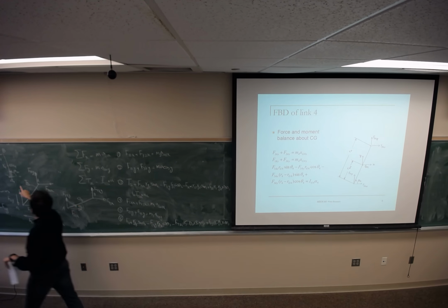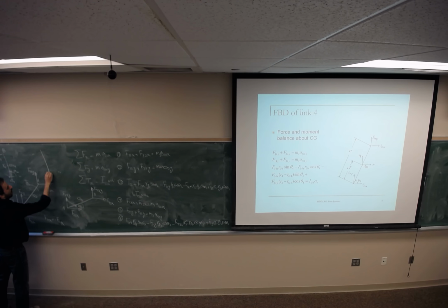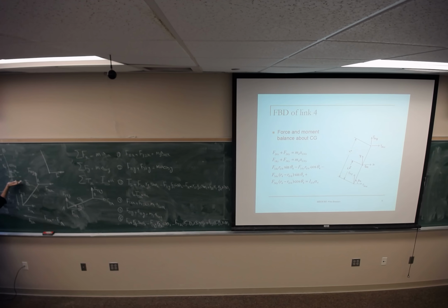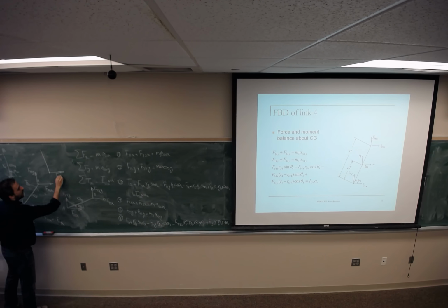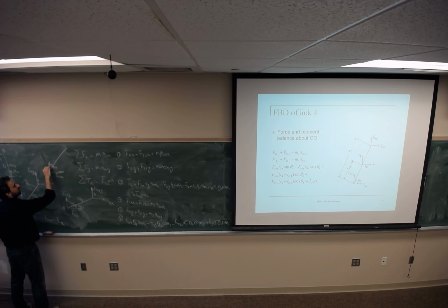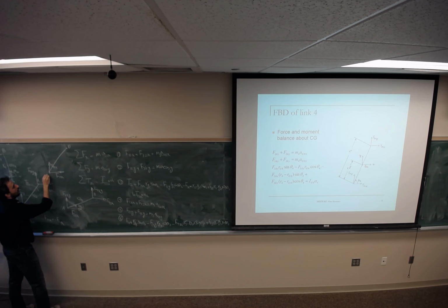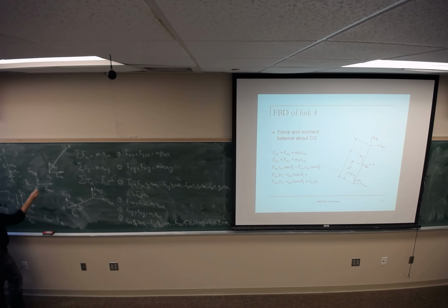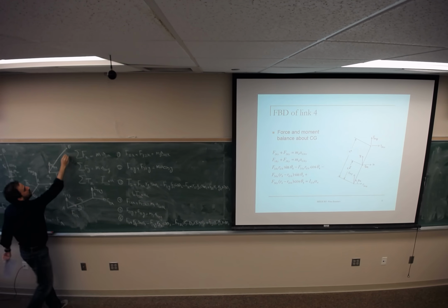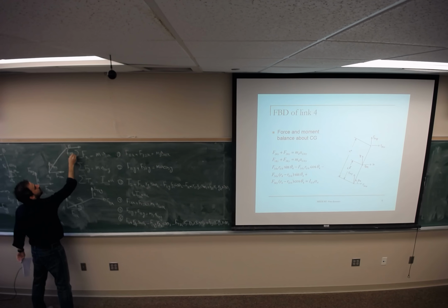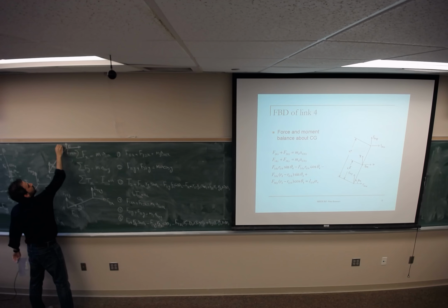At point O4, the force coming from link 1 applied to link 4, F14x, F14y. Let me write it down. This direction. And here at point B, the force coming from link 3 applied to link 4 in x and y direction.